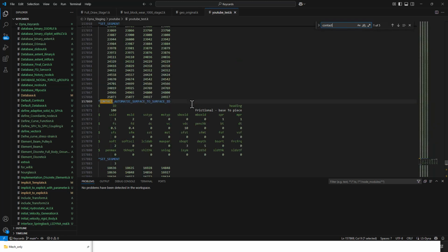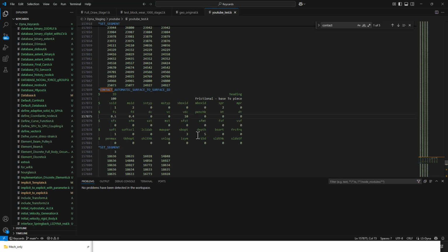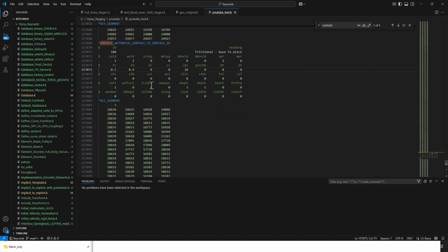And of course, the first thing we want to do is to make sure we set our contact solve to 1, and I want to set our SPR to 2, and I'm going to set MPR to 0, right? So that only the SPR, which is the contact side, the die piece, is going to be written out in the final model. And if you look at this model, this is basically the only change we have to make.